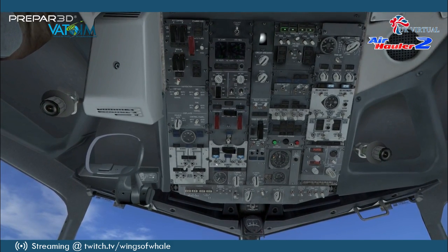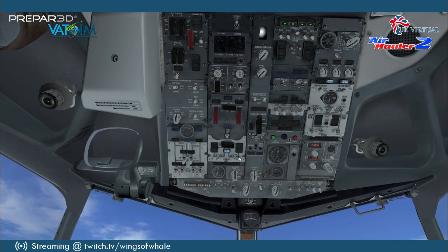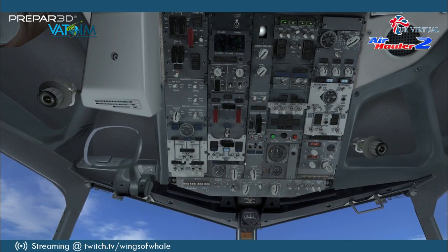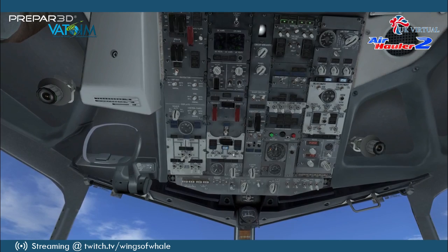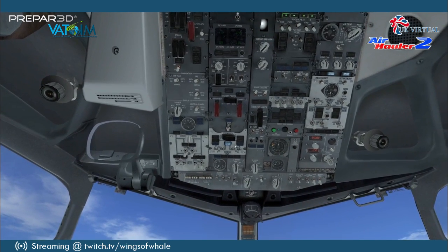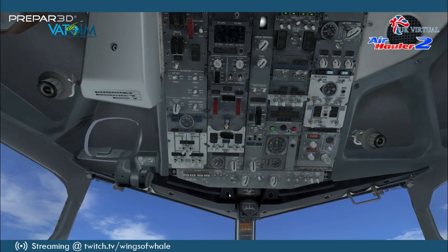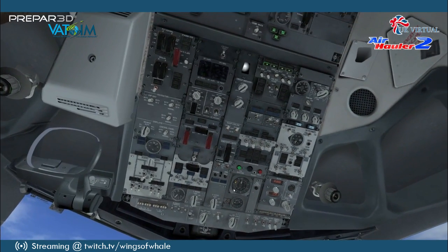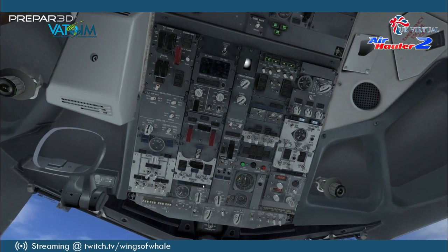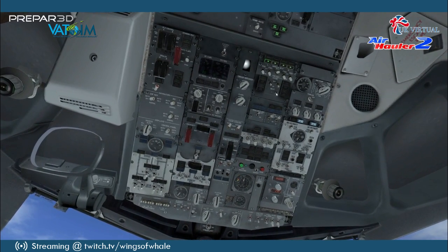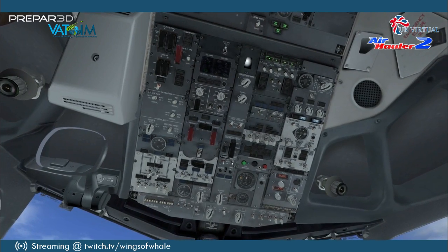So what we do first is we turn on the engine generators, which is those two switches there. So now the engine is providing the electricity to the aircraft, and you can see the APU lights are lit up now, showing that the APU is off but available. So you just flick the switch to off on the APU, and you'll see the lights go off. So now on our panel we have no orange lights, no warning lights, nothing that indicates an issue.